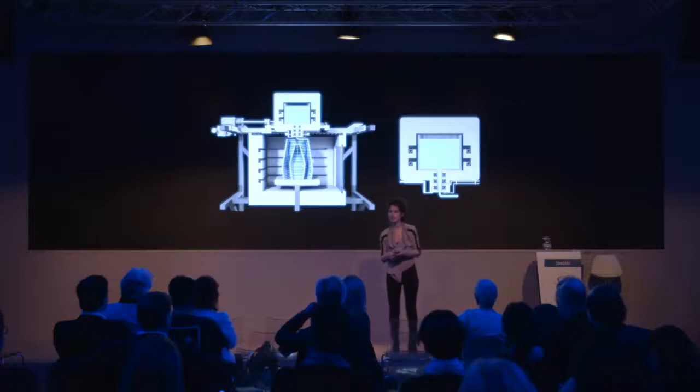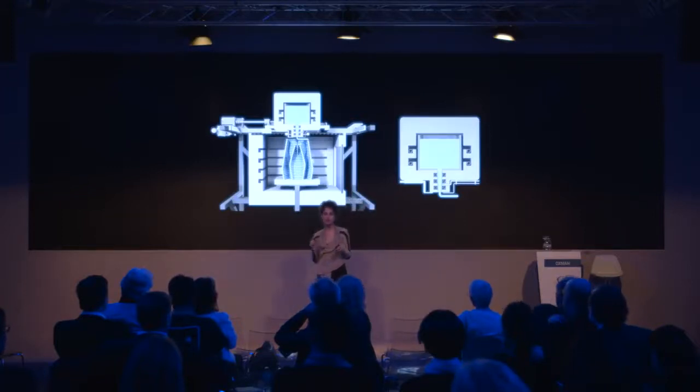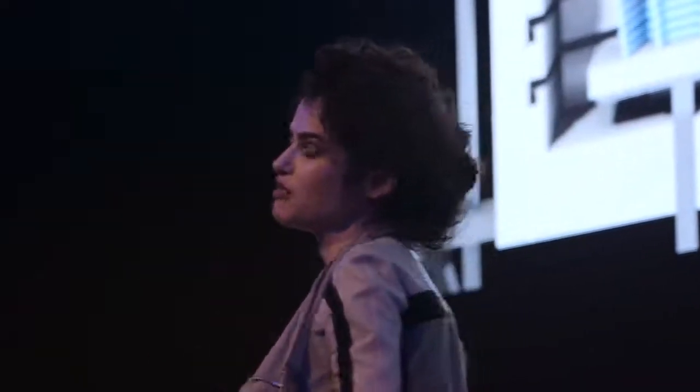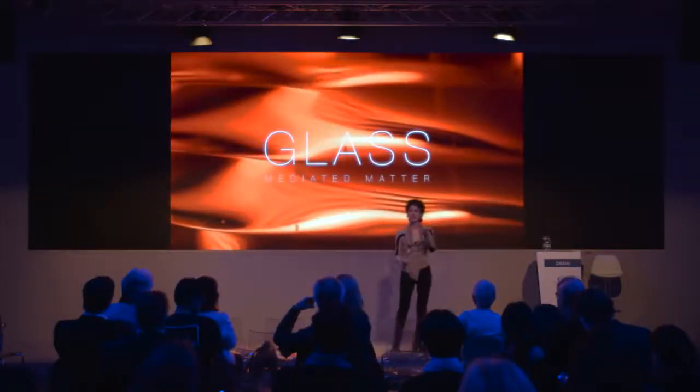Before I show the video, this is how the printer is designed. It has a kiln cartridge that allows us to take in molten glass and control the gradient of temperature, thereby controlling the viscosity of the glass, thereby controlling the geometry of the deposition. So it has a crucible kiln. It has a kiln around the nozzle with thermocouplers that allow us to control the variation of temperature as we're controlling the viscosity. Let's play the video, and I hope you enjoy. I will interject with a few words as it's played, so please volume up.